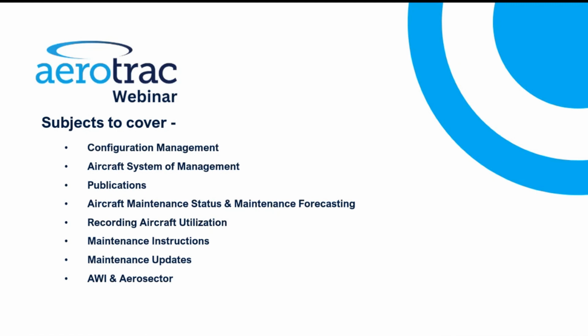All of that pulls into what we call the aircraft maintenance status or aircraft status screen, which allows you to drive through and do forecasting. You can update the status of the aircraft in terms of its hours and cycles using the aircraft utilization functions. Beyond that, you raise what we call maintenance instructions, which are instructions to the 145 as to what work you need carried out, and then update that through maintenance updates, which say yes, that inspection, that publication has been carried out, that life limited component has been changed or overhauled or whatever.